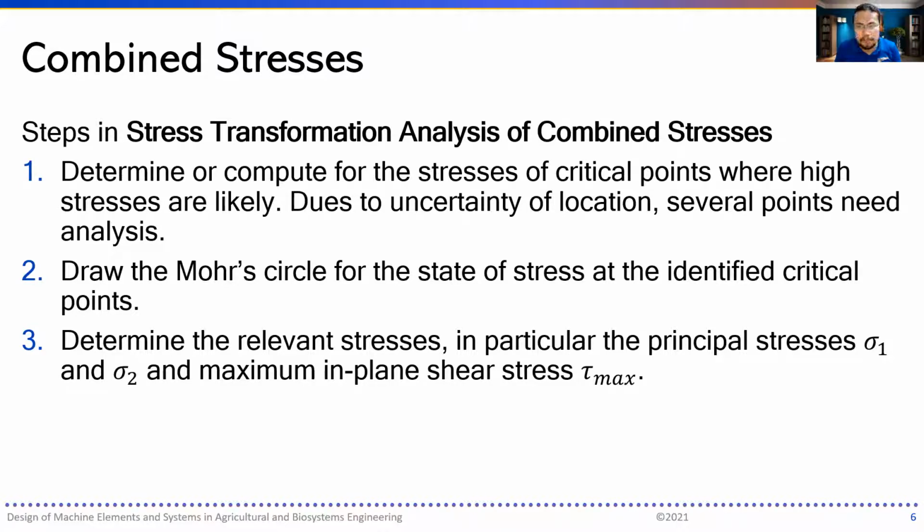And once the critical points are identified, it's important to draw the Mohr circle and eventually solve for the principal stresses and the maximum in-plane shear stress. Now, this technique to simplify the stress transformation using the Mohr circle is a very handy tool in solving for the principal stresses, or the stresses that are of critical importance in machine design, because the bodies in